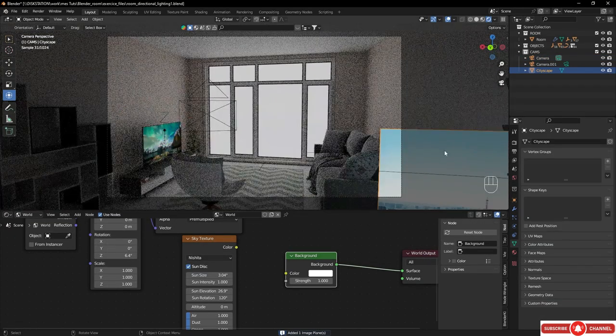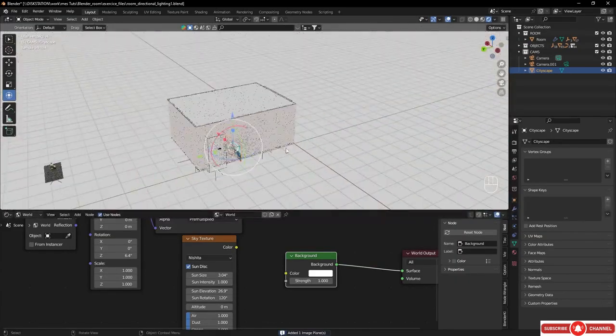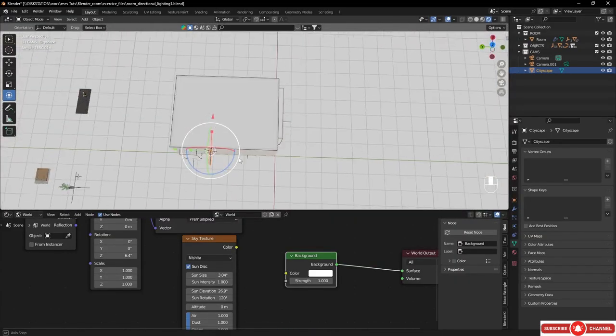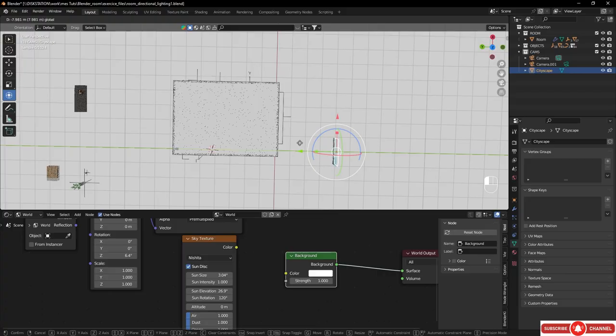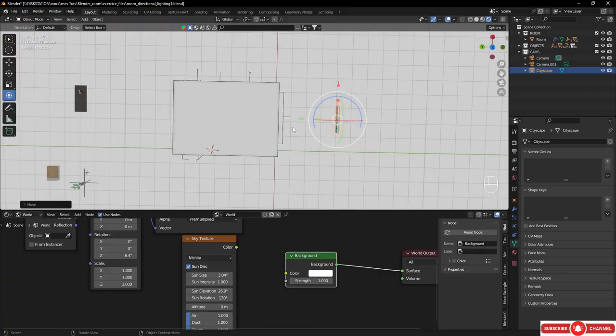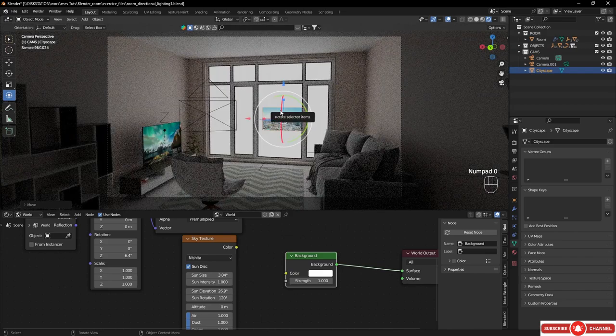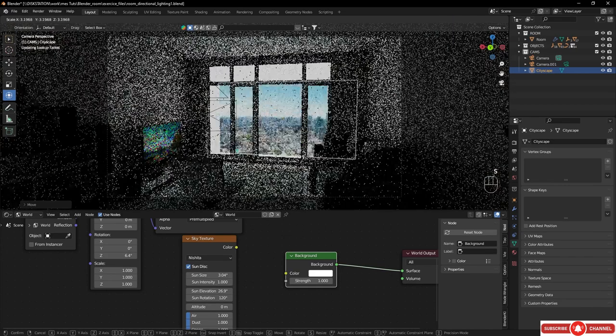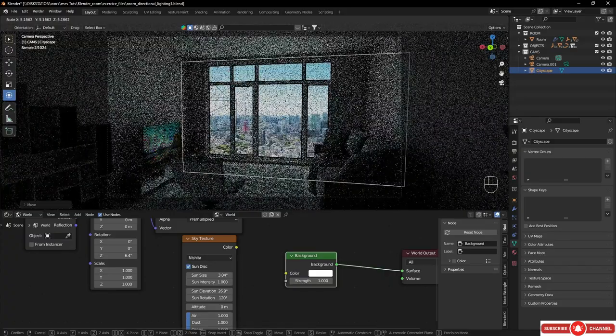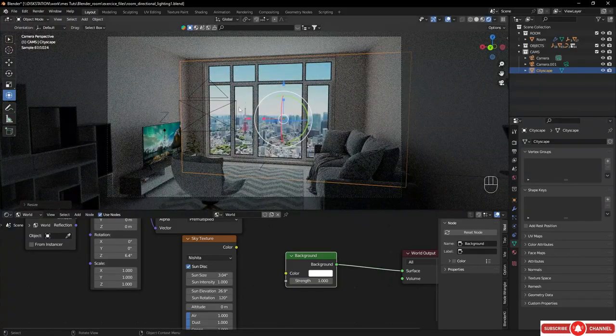So now it appeared right here because this is where our 3D cursor was. So let's just move it somewhere there. Let's switch back to our camera, typing 0 on the keyboard, and then we're able to just scale it. So let's scale it so that it fills the frame. So I think our horizon plane is something like that. So I try to match it with our scene.